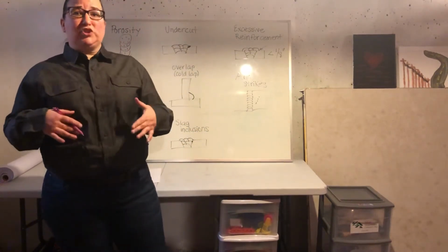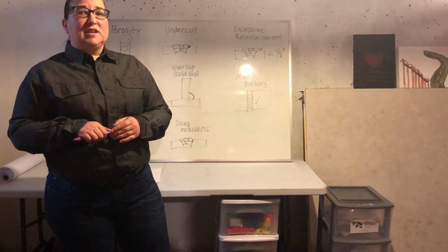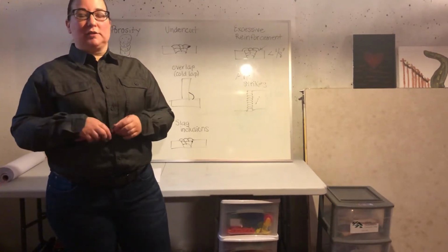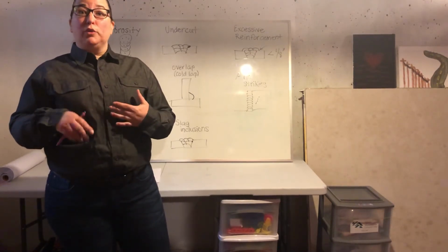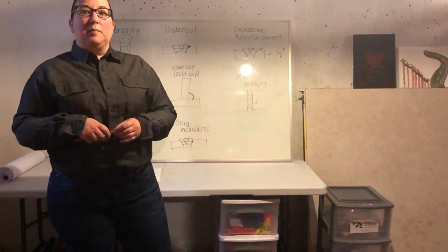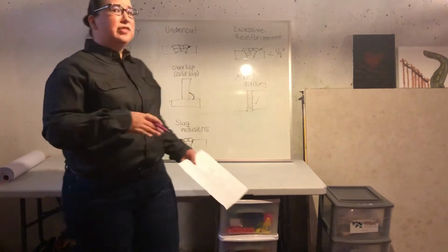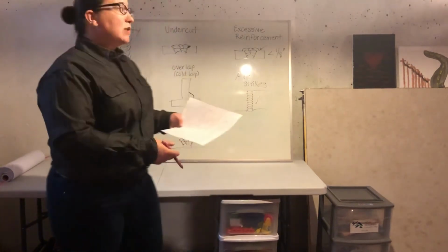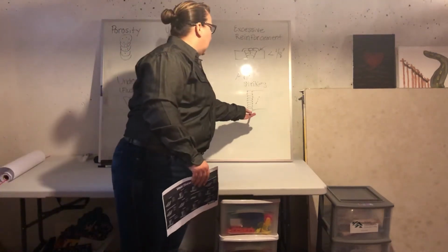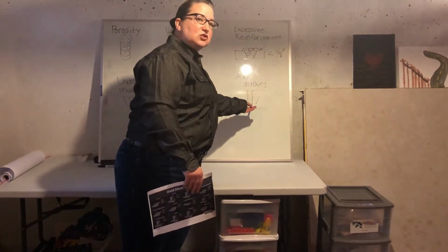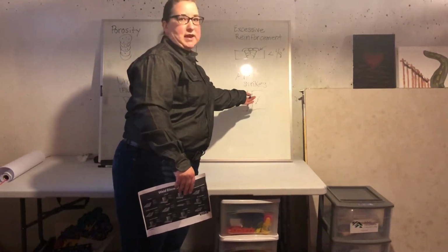So once we've got our machine and we're all set up and good to go, we want to make sure we're paying attention to what I like to call the human errors. So these are all of the things that are controlled by the welder through his or her movements and positioning. So some of those start with things like travel speed. So as we travel along a weld, say I'm doing a vertical weld here, I want to make sure I have a nice consistent travel speed to where I'm depositing the filler metal at a nice even rate.